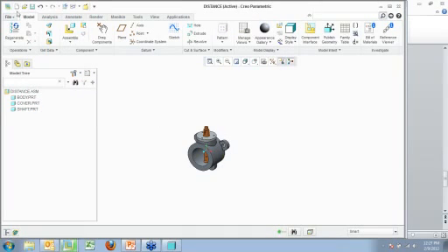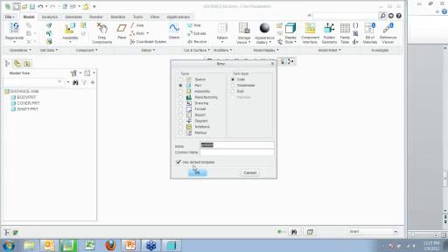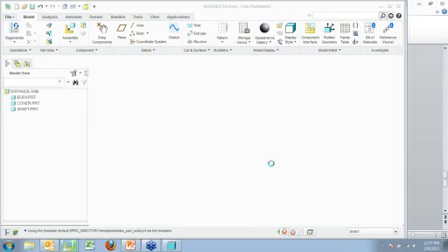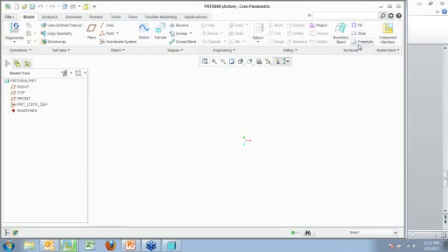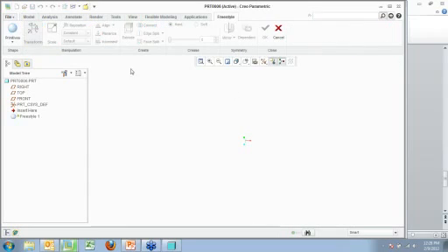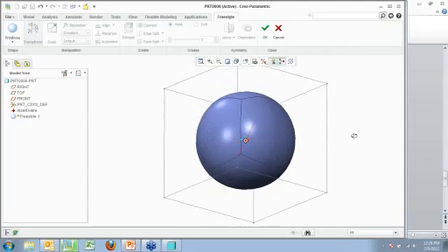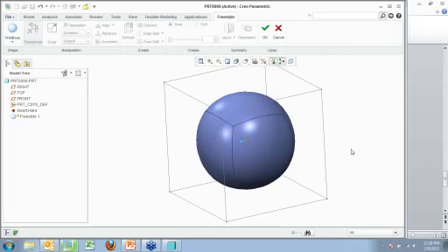So now let's talk about freestyle modeling. Let's start a new part. And Ben did cover this a few weeks ago, a month and a half or so ago. I think this is really cool. It allows you to do push-pull kind of modeling with clay type options, where now I can go in and manipulate things, make some pretty complicated geometry that before, if I was just trying to do in Pro E or Creo Parametric, there'd be no way I could model some of this stuff.